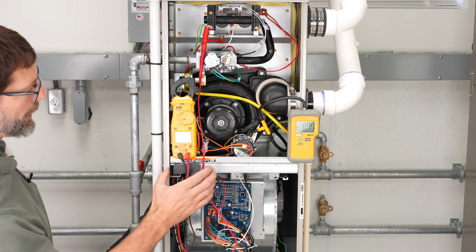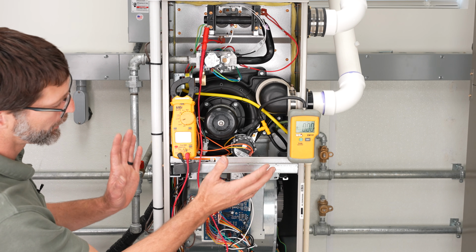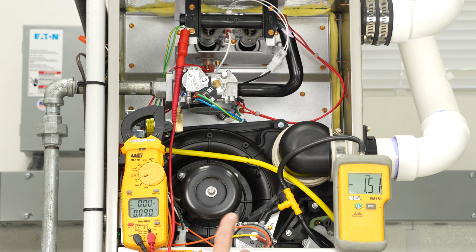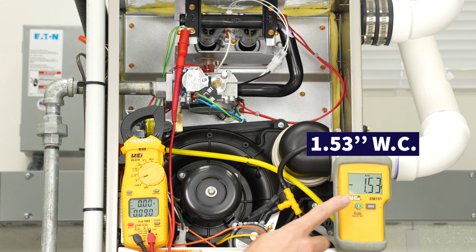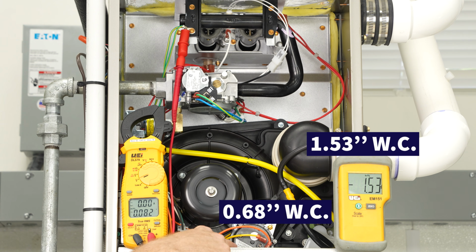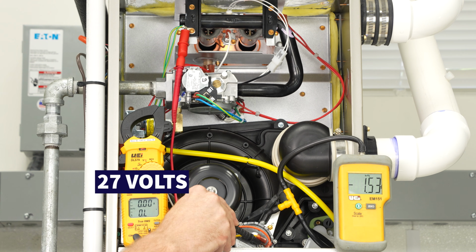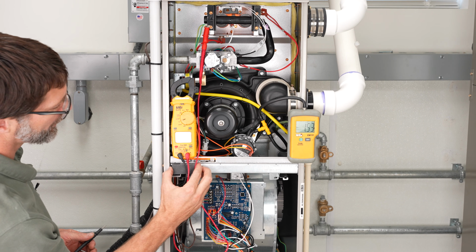So we're going to go ahead and turn that on, and we're going to skip past the time where the blower would need to run for 90 seconds. So you can see that the inducer motor is applying 1.53 inches of water column against that pressure switch, which is only rated at 0.68. So we know that it's good and everything's operating correctly. Let's measure. So we got 27 volts there and 27 volts here. So everything is good. I'm going to go ahead and shut this off.